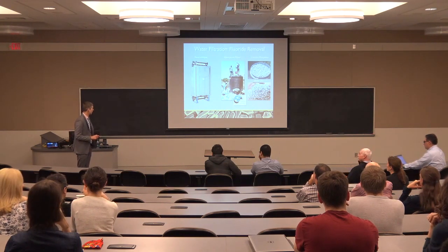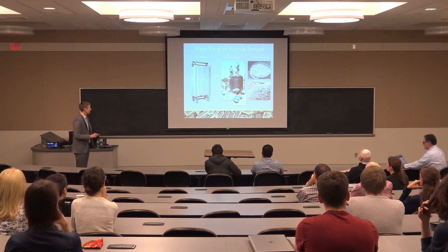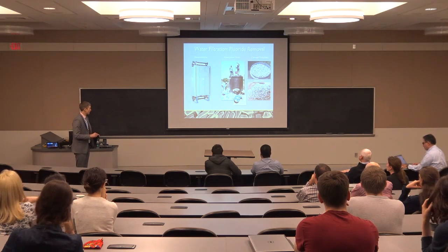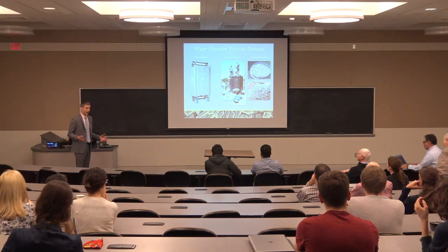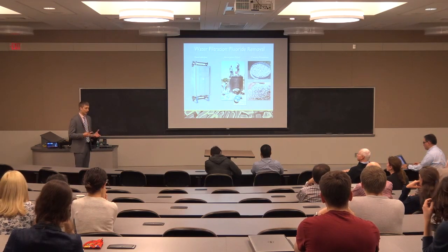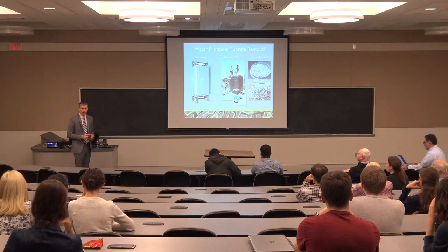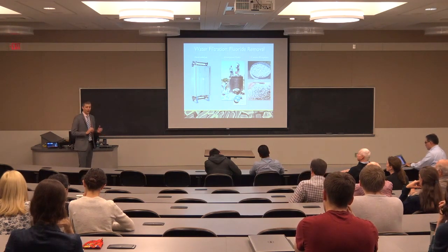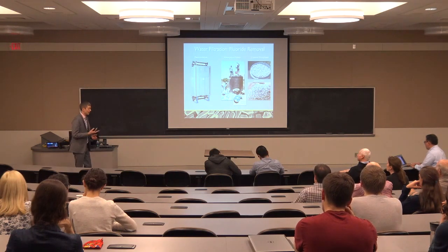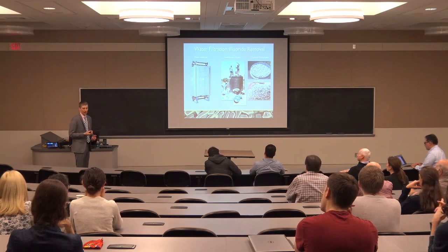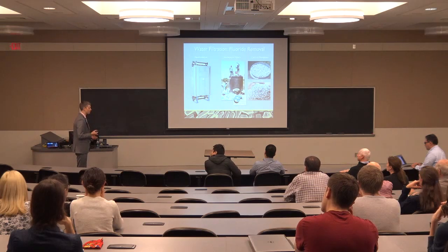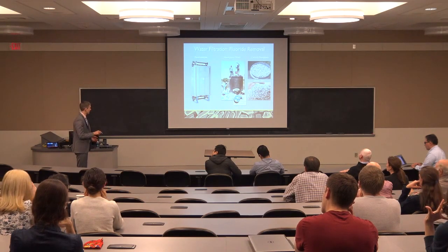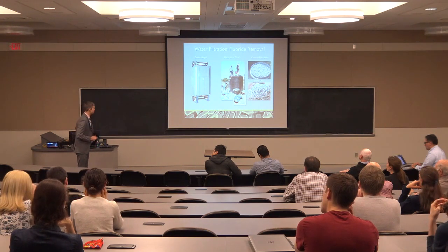And the solution that they've come up with are these absorption filters. They use some calcium phosphate to absorb the fluoride, but the really magic material is this stuff called bone char. They take cattle bones, they heat them up to high temperature in a slightly reducing environment. In the lab, we'd call that pyrolysis. And they end up with a very finely porous, high surface area material that turns out to be very good at capturing the fluoride present in the water. The same way that our bones would absorb it, and it would degrade the bones, instead, this bone char material absorbs it, and it solves the problem.